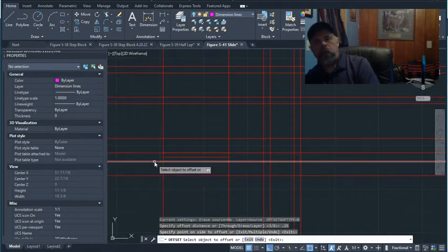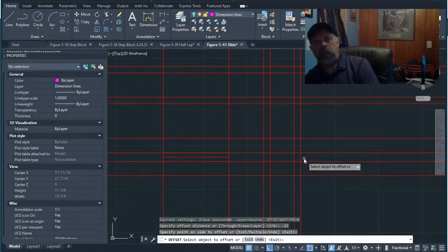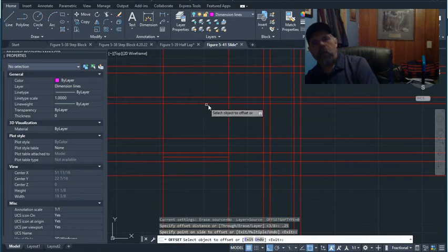I'd use my construction lines coming across here to lay those slots out. Then I'll set my line from the top of my front view up 2 inches to start my top view. I'll set that 2 1/8 or 2.125.